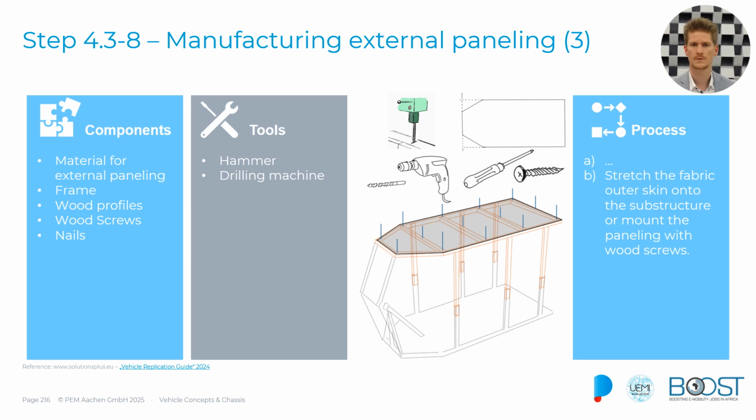And then, at the last, if you use some fabric, you can stretch it around the outer skins, and then just screw it or bolt it or staple it to the wooden frame. If you do so, please remember fabric is probably just more of a sun shield and not a protection against any rainy kind of things, but therefore is very light.